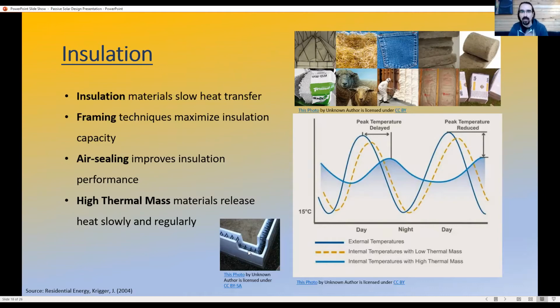This picture here is an insulated concrete form. So when the concrete is poured into these forms, it is insulated on both sides. This is an expanded polystyrene insulation material. And that creates the density of concrete to hold that thermal energy, and also creates that insulation layer that keeps that energy from conducting to the outside quicker than we would like.